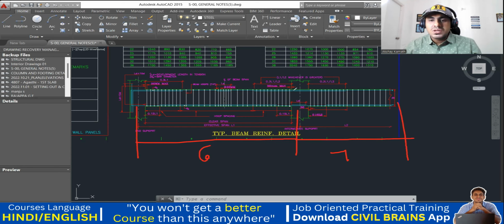Because actually, if I'm looking for this side, I need to consider 6 meter. If I'm looking on right side, then I have to take 7 meter. So what the code says, don't do like that. Out of L1 and L2, this is L1 and this is L2. Whichever is higher, you take that. So 7 is higher, no? So 0.3 into 7 you do. And whatever length you get, you provide up to here, top right. And top left also, you take 0.3 into 7. That is what the code says.